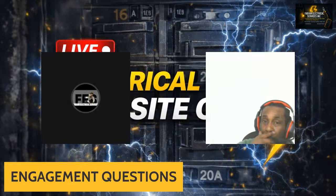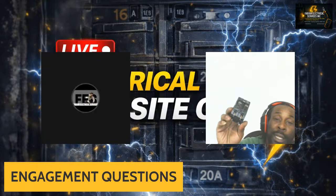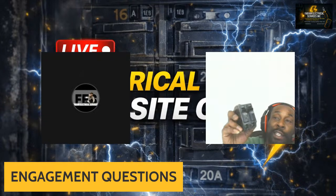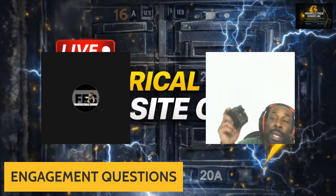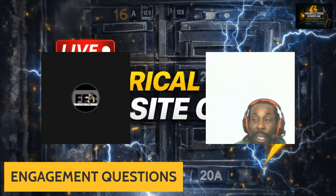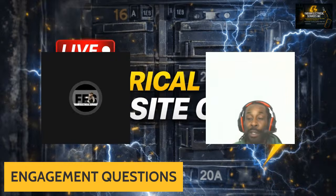And this is basically the 20 amp. This is a 20 amp 2-pole. You will use this on the 2 hots. Let's say you have a split receptacle in the kitchen. A lot of times it will be a 15 amp split. This is a 20 amp. This is best used for air conditioners, heaters and so on, higher voltage, to actually make the circuit work accordingly. So this is what this is.